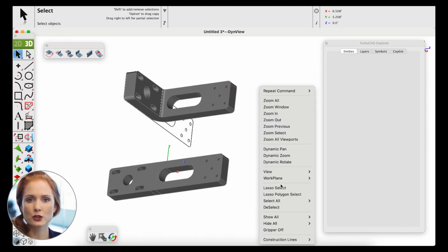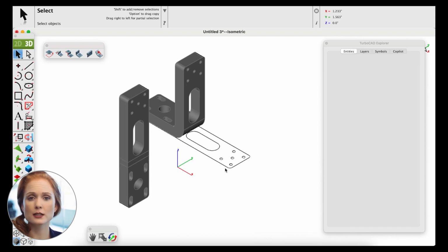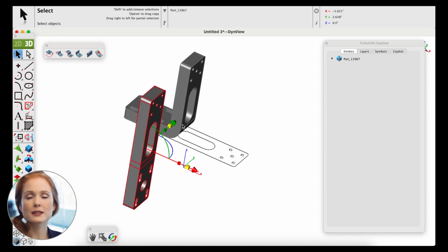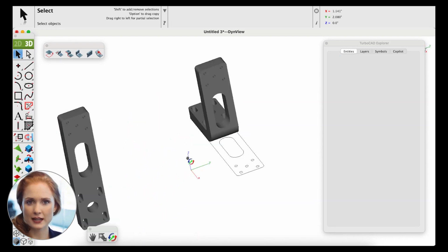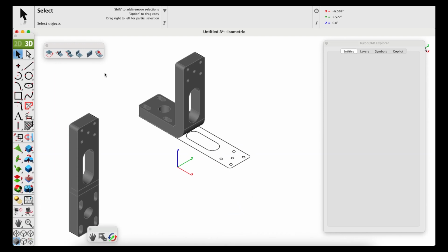The unbend feature enables you to return a bent or curved section of a sheet metal part back to a flat, planar state without altering the overall design. Select the unbend tool and then choose the solid geometry you wish to unbend.